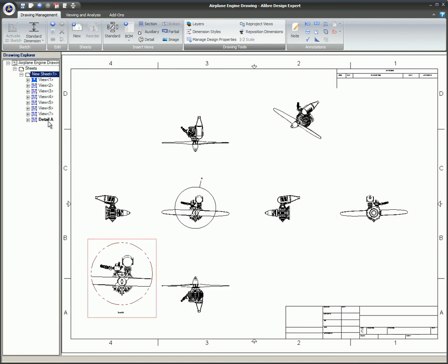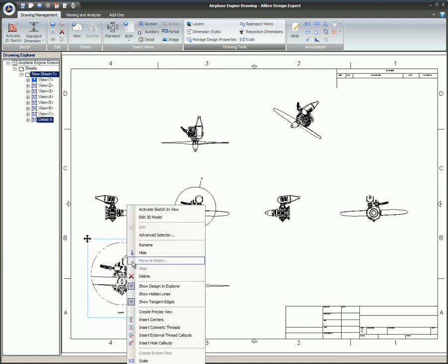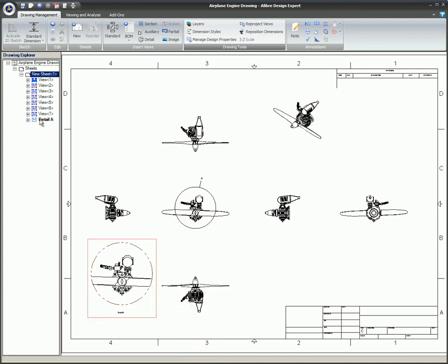This video covered precise and fast views. Precise views are the standard views that should be used most of the time. Fast views are used in drawings for use with large, complicated models and assemblies. These views do not project the edges of the models, but insert the view of the actual model into the assembly. Both types of views should look very similar to one another, although precise views should look sharper and crisper.